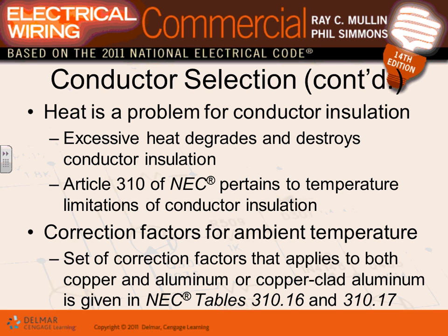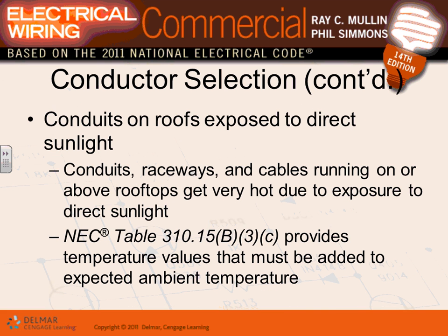That's why all this talks about ambient temperature and applying ambient temperature for covered conductors, and we will do some of these. If you have conduits on a roof, you also have to derate based on how high the conduits are set on the roof of a building. Why?